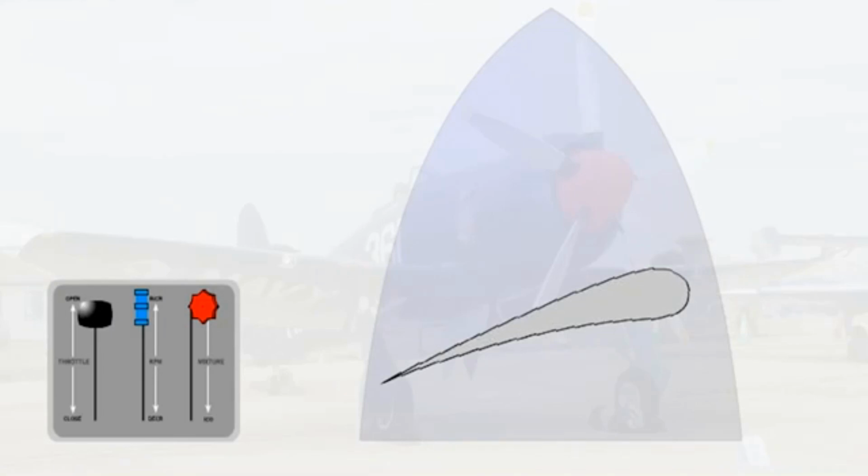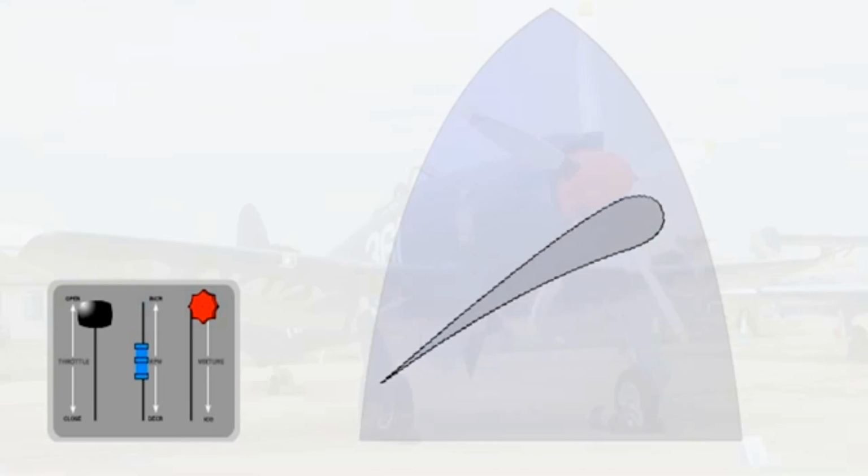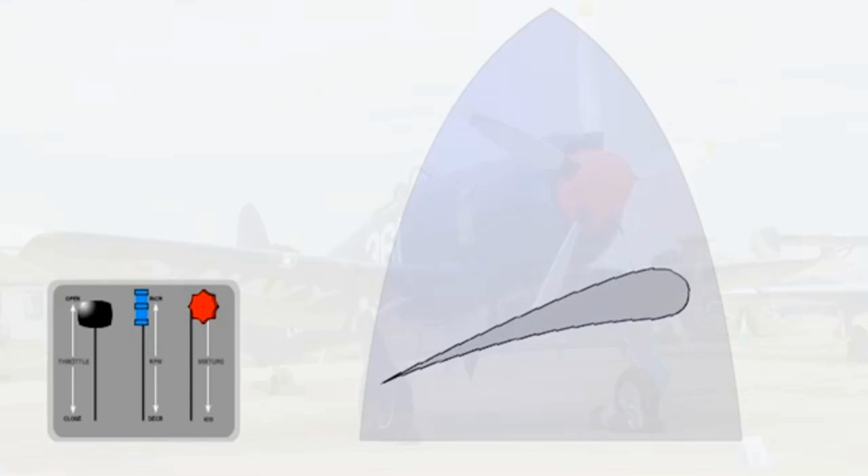This diagram illustrates a typical set of engine and propeller controls for a small piston-engine aircraft with a variable pitch propeller. Throttle, propeller, and mixture are shown in the takeoff, all-forward position. For a given throttle setting, pulling back on the propeller control will decrease RPM by coarsening the pitch of the blade. Conversely, pushing forward on the propeller control will increase RPM by fining off the pitch of the blade. Once RPM has been set, it will be maintained within the operating range of the throttle lever.